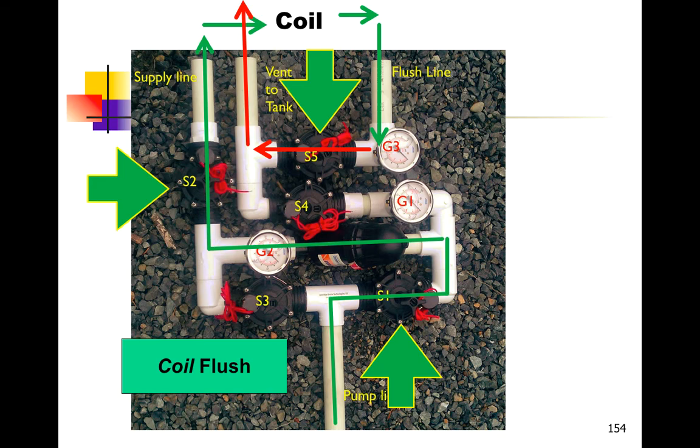And the flow in the septic tank in relation to the backflushing of the filter will be about half the flow. We have lots of friction loss and we have some flow loss in the low flow coil, so we would expect to see a lower flow discharging into the tank with the coil flush.